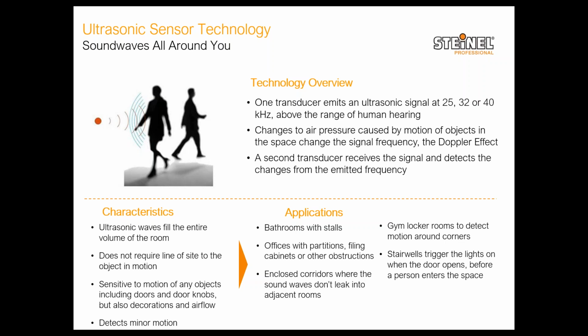Because when you have a PIR sensor, you have to actually take a step in. You have to open the door, take a step in, at least one step into the staircase, and then the lights turn on. Whereas when you have an ultrasonic sensor in the staircase, as soon as you start pushing the door, lights have turned on, the sensor picks up that big rush of air and the movement of door or door handle and will turn on the light.